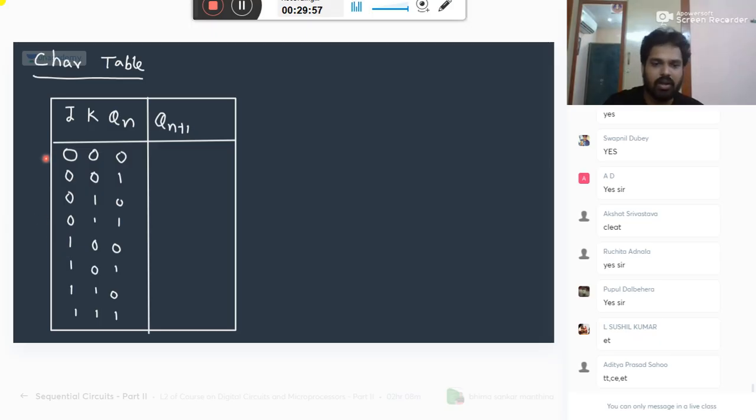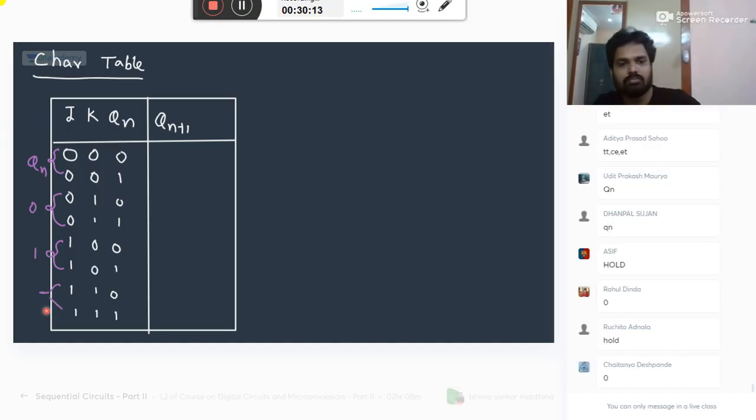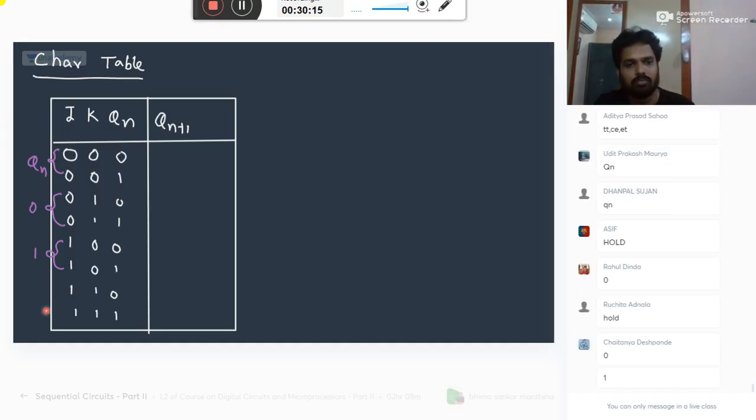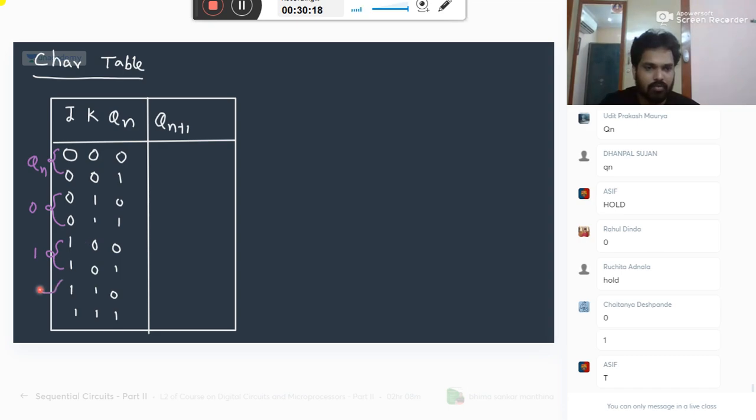Okay, I already told you one thing. For 0, 0, what is your output? No change. For 0, 1, it is 0. For 1, 0, it is 1. For 1, 1, it is previous bar.